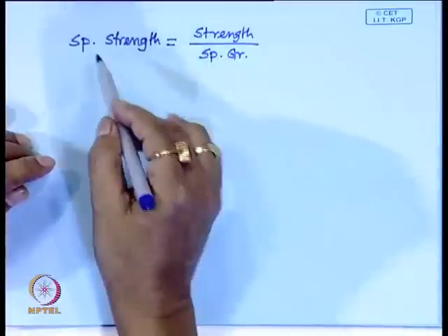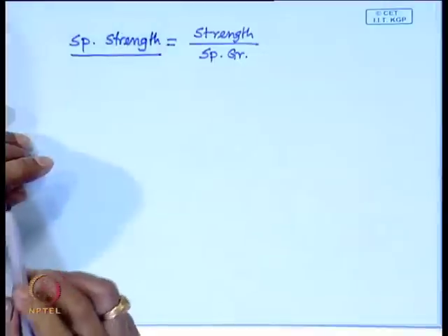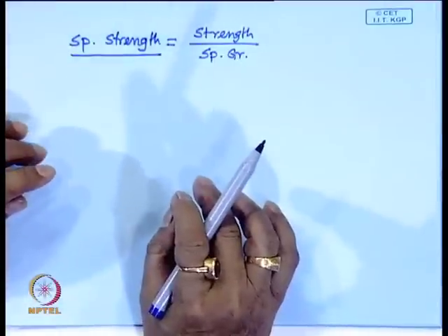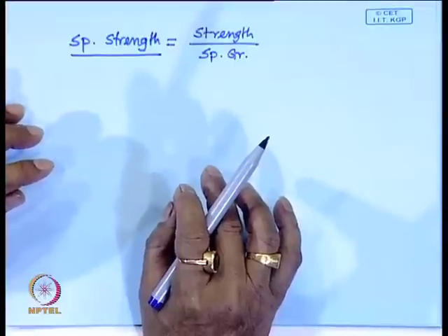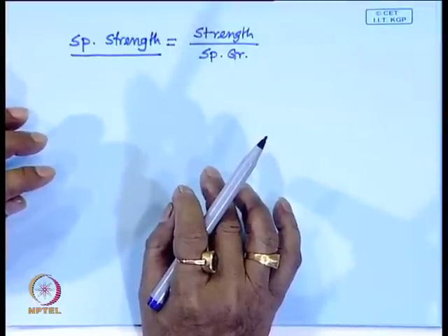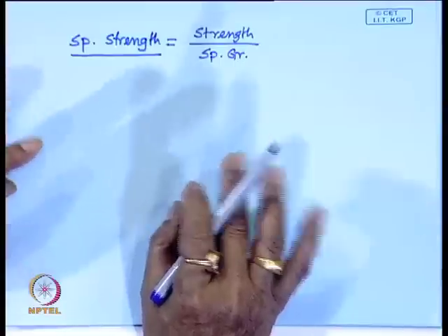Now, you take one polymer sample, say even a natural fiber, for example, jute fiber, its tensile strength is suppose 450 megapascal, and its density is around 1 to 1.1 to 1.2. So, polymers have still lower density. Since the density is low, specific strength is very high. Now, this is a property which is very much essential in today's civilization, in civilized applications. We can get very high strength, but light.